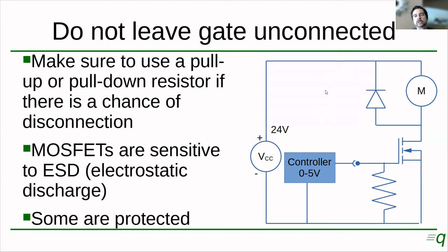The other thing that you have to keep in mind is that MOSFETs are sensitive to ESD, or electrostatic discharge. Although some are protected. We mentioned that MOSFETs are used in quantities of millions in computer chips. Now, computer chips are also sensitive to ESD, but the inputs are usually protected.